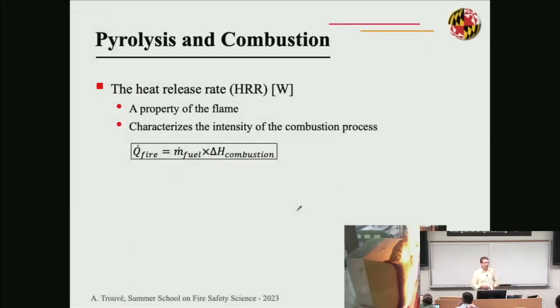All right. What about the heat of combustion? The heat release rate is going to basically follow the fuel. So once this fuel is released by thermal degradation processes, and assuming that we have enough oxygen to consume all of that fuel for combustion, that's an overventilated fire condition assumption, which for wildland fires is usually adequate.